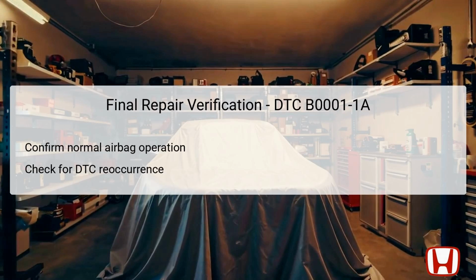After completing all troubleshooting steps and making necessary repairs, it's important to verify that the airbag system operates normally. This involves reconnecting the battery and performing a self-diagnosis using the Honda Diagnostic System, HDS, to ensure no DTCs appear.